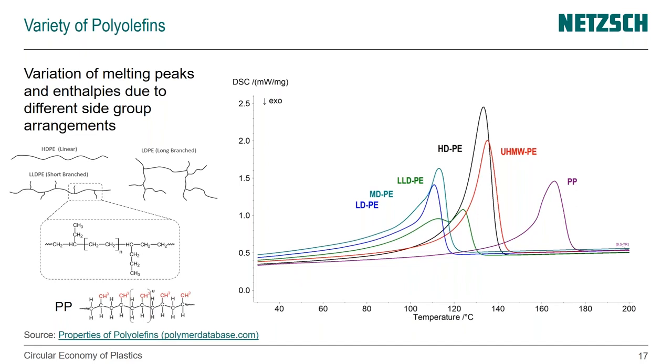And can you differentiate a PP copolymer from a PP homopolymer? Not really. The distinction between them could be a little bit in the peak shape, but the deviations, as I was trying to show, are already pretty significant between grades themselves. So the molecular weight definitely has more effect on the peak temperature and the shape than the copolymer and homopolymer. So I don't think that's possible. We haven't tried it. That's just from what I've seen.